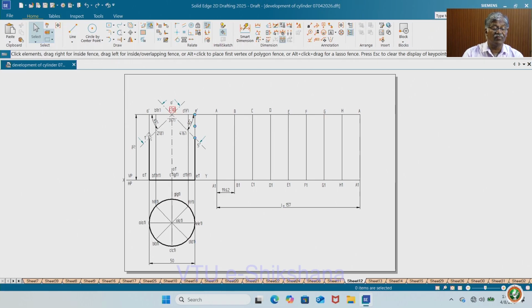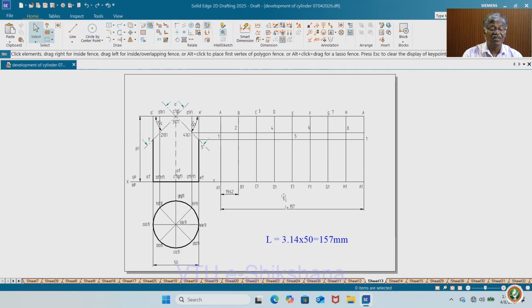So you have to start from this 45° and 45°, leaning downwards right and downwards left, then identify the points and divide the base into 8 equal parts, of the same dimension. The same type of pattern is there in the overall development. Then project all these points. You will get hardly 3 lines of projection: 1, 2, 3. The top line coincides with the top face perimeter. Now this is 1, 2, 3, 4, 5, 6, 7, 8, 9; this is not 9, actually it is 1.